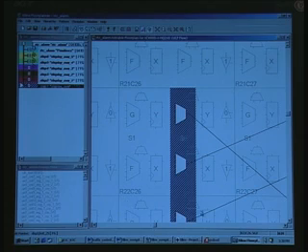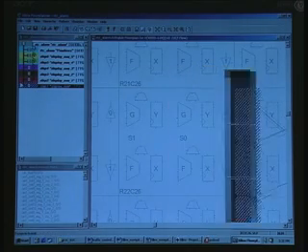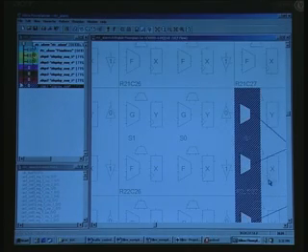So, you can call this one logic block, or I do not know really what that terminology is, Xilinx terminology is. Suppose you want to relocate this one from here to somewhere else, let us say here, you are free to do so. So, you have the flexibility of changing, that is vetoing the Xilinx place and route, what it has already done. You can overrule that one and place it elsewhere.